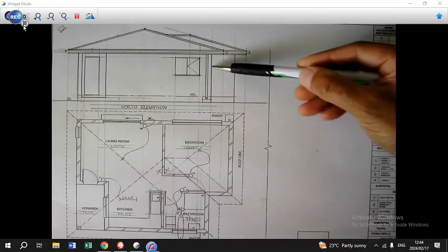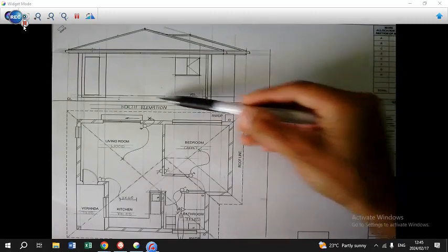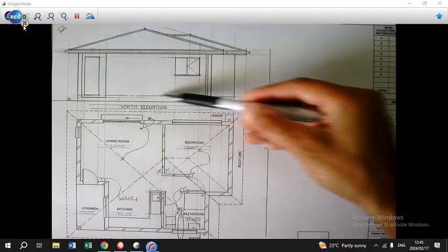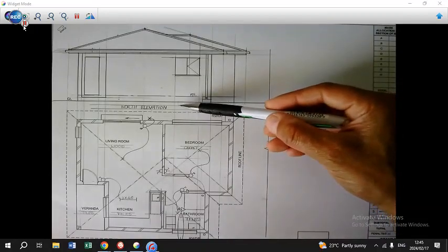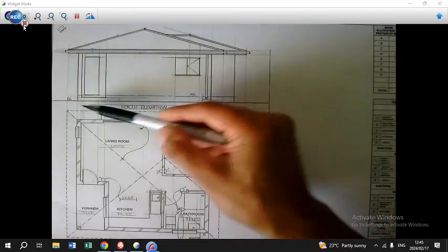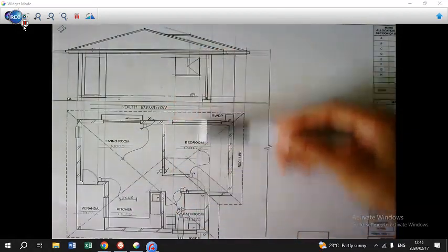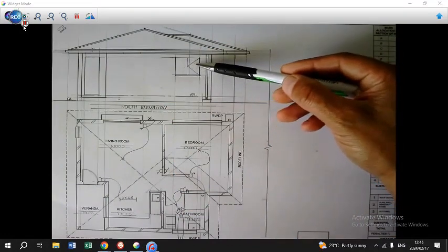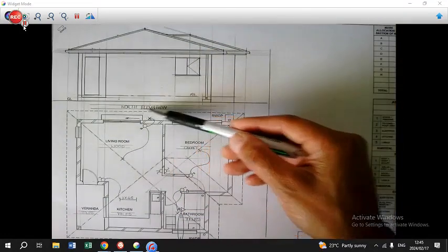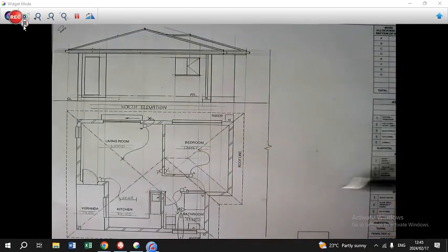We have our finished floor level, from which we have determined that from our section view. And then of course we have our door that we have projected up, and our window, which this side is the fixed side and that side is the opening side. And we concluded with the labels of north elevation and the finished floor level. Let's draw our attention now to the following detailed section drawing on the right hand side.